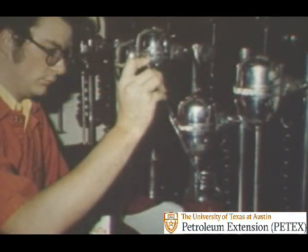Here, in a portable laboratory, the engineer is slowly adding an acid to the oil mud to check the mud's alkalinity. Out on the rig, lime is usually added to keep the alkalinity within the desired range.